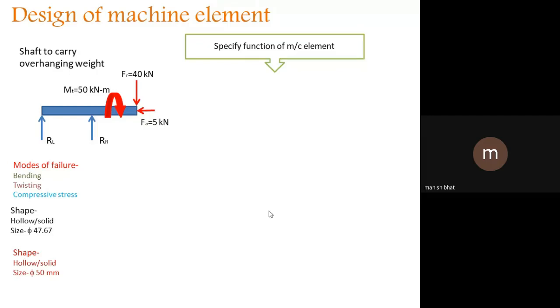So what is the function of that lever of the safety valve? The lever of the safety valve is maintaining some load, some pressure, creating some pressure over the hole provided inside the boiler. If that valve opens, steam will come out, and steam should not come out up to a particular pressure. Suppose that valve is designed to blow off at 175 bar pressure. Till 175 bar pressure is reached, it should keep that particular opening closed.